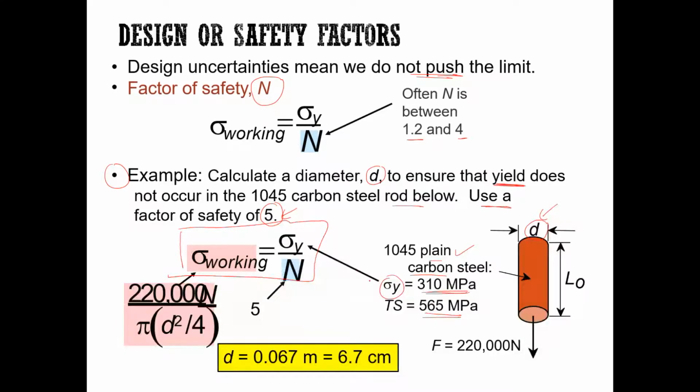So we plug these values into sigma Y over N to get the working stress. And we know that the working stress is equal to F over A naught.